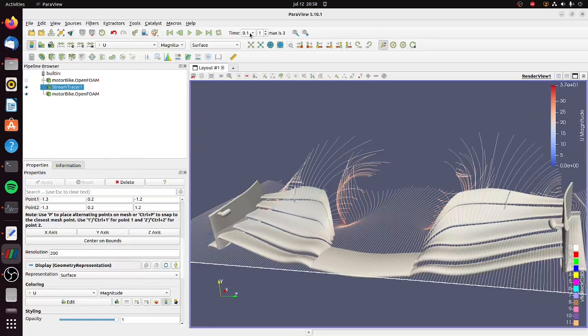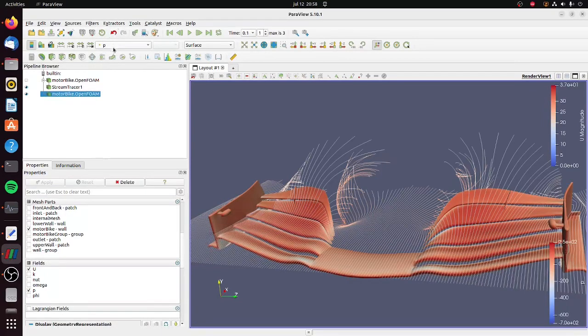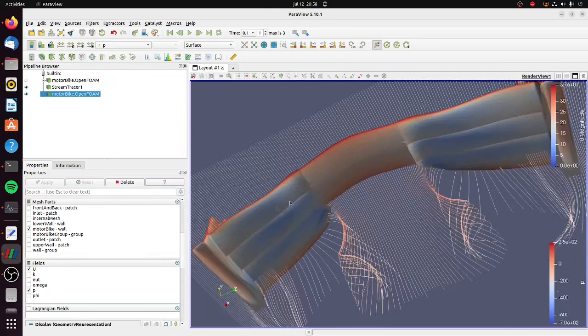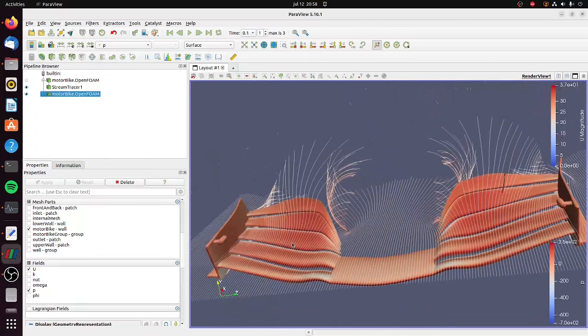We can also go to the next, let's actually first do here. We can see the pressure on the wing. There's two pressures, make sure you do the one with the dot. 0 is the pressure that was coming in, and then negative would be blue, and that's like pulling down. So here you can see all this blue that's pulling down the wing. Amazing. And all this red pressure pushing the wing down, so this is how you have force. Up to 250 pascals, quite a number.